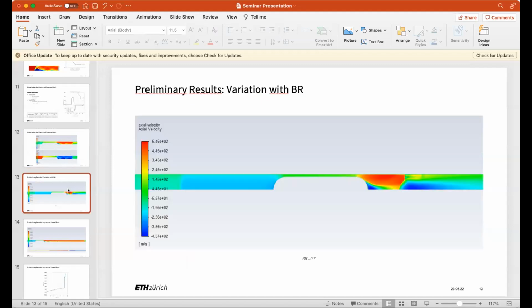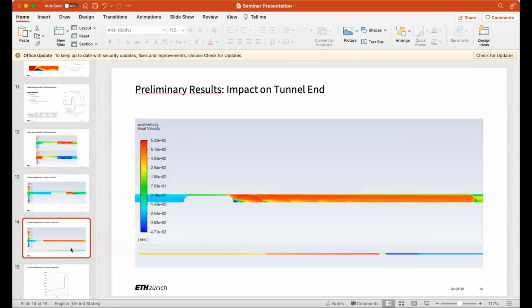And then on these final ones where we're actually trying to simulate the Hyperloop tube, we have a wall at the end, a no-slip wall at the top, and an axis at the bottom, of course. And at the end, we have again a pressure outlet, which obviously is not really physically an outlet, but it's just there to impose the given pressure that we have in the tunnel. Nice.